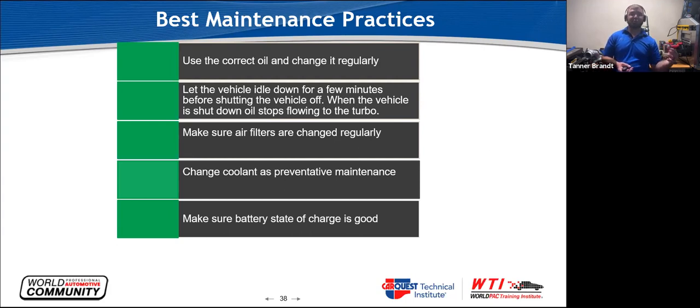Tell the customer they really need to let the vehicle idle down before they shut it off, in hopes that it's also going to slow the turbo down. The oil's still going to be flowing across it, and it's also going to help cool it a little bit. Make sure the air filters are changed regularly. I would really prefer that they get changed on a turbo car every 10,000 miles to make sure we're never having the issue of a restriction.